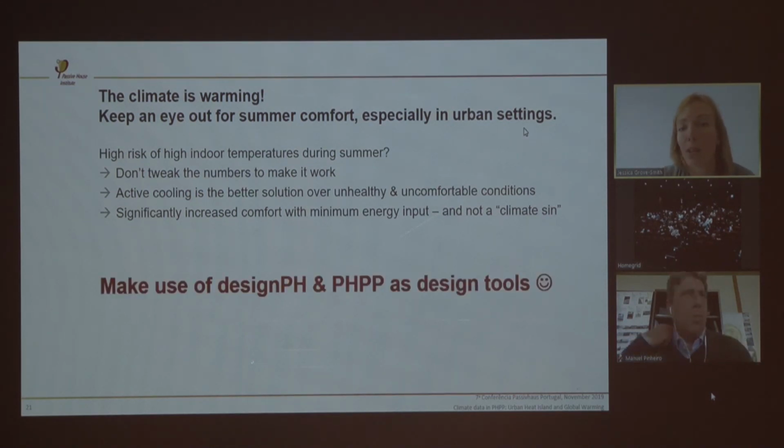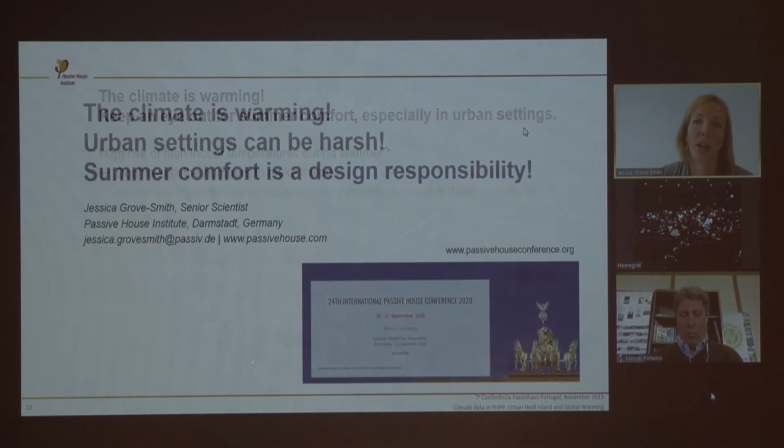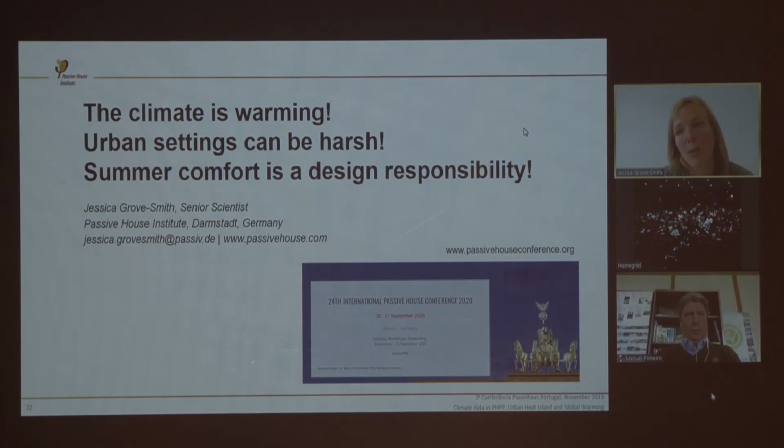Generally, make use of Design PH and PHPP as design tools. They are extremely valuable. And they will give you guidance in terms of where you stand and how you can improve your design to account for these. Things can be extremely harsh in terms of summer temperatures. Summer comfort is a design responsibility. So I hope I was able to give you some input on how we recommend to deal with these aspects.